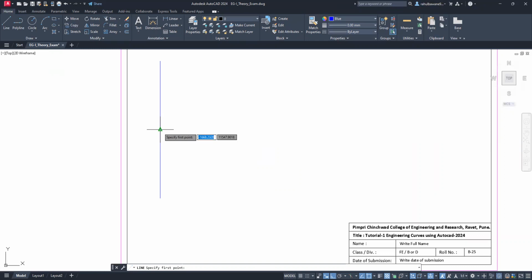So I want to draw a horizontal line from this midpoint. I pick the first point in this triangle and drag the cursor to the right, and approximately this length I end it here. Now my cursor is here, but as I picked this command, only 90-degree lines are drawn, either horizontal or vertical.